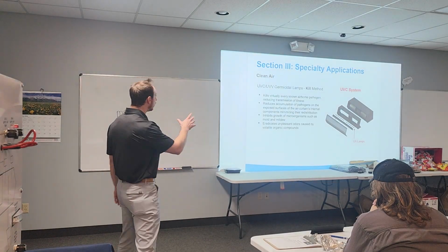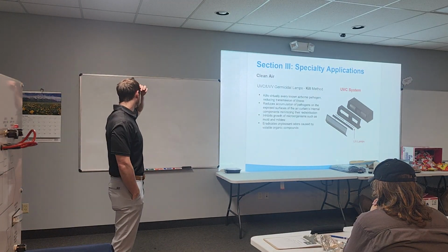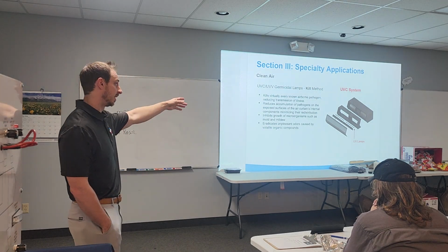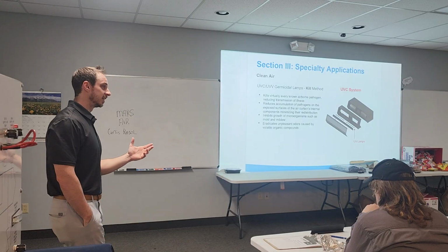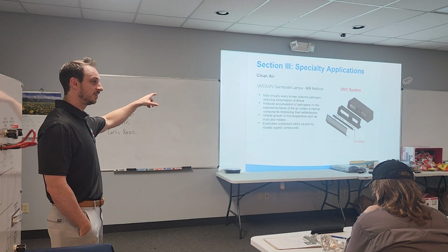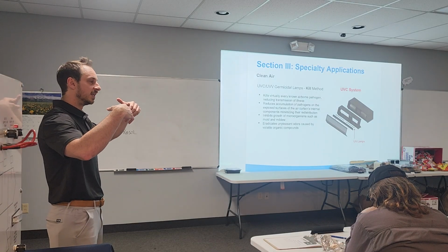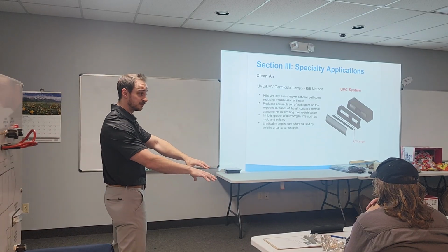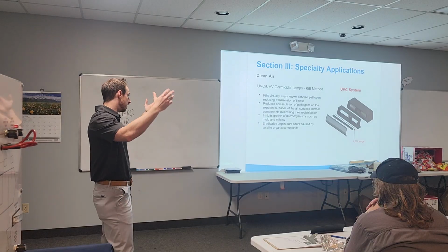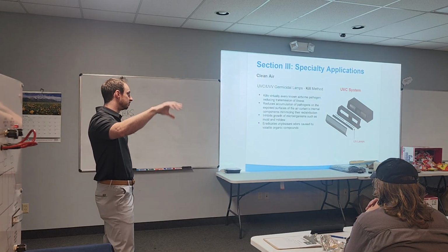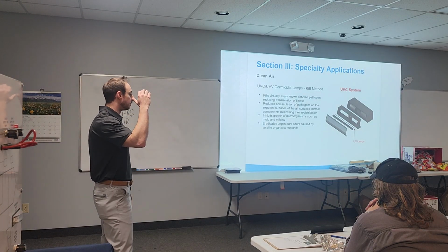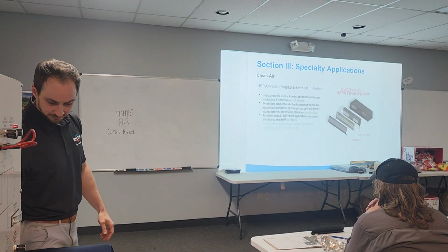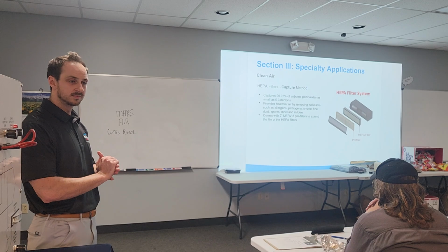Clean air, yeah, I'll skip over this one a little bit. I already talked about UV, but that just gives you an exploded view of what that looks like. So it's really just one of the units with some UV lights. That's what we call our kill method of clean air, meaning the air's coming in through the intake stream. How UV works, obviously it kills surfaces, it doesn't kill it out of the air, so those particulates and pathogens are getting deposited into the housing, and then the UV lights are hitting them and killing them there, and then discharging clean air.